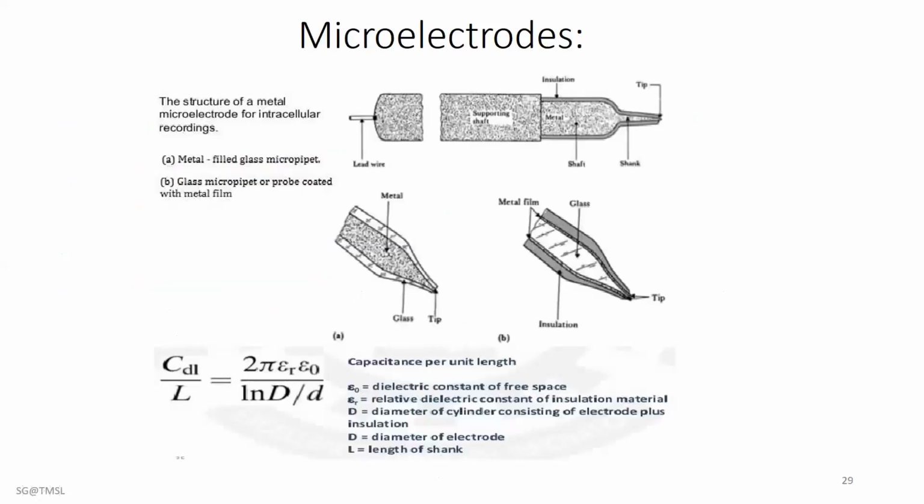Here is a diagram of a micropipette type of electrode, which is actually a glass micropipette with a tip of the desired size, about 1 micron. The micropipette is filled with an electrolyte suitable with cellular fluids, and such micropipettes have a dual interface.